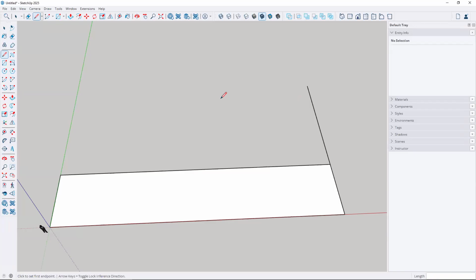And then I'm going to use my space bar. So I have the line. And then the next thing I need to do is draw a rectangle, and I'm going to take advantage of this endpoint. So I'm going to click on rectangle. I'm going to click right here on that endpoint, and I'm going to bring it right over in this direction like this. And that creates the rectangle. And then tap the space bar.